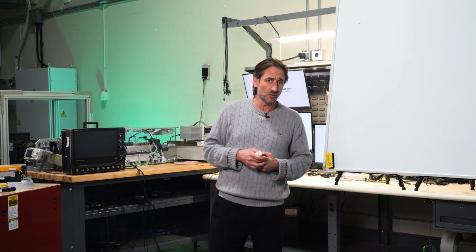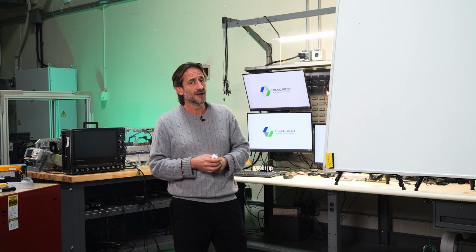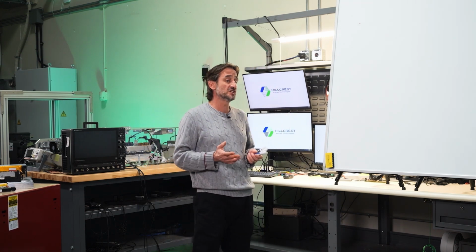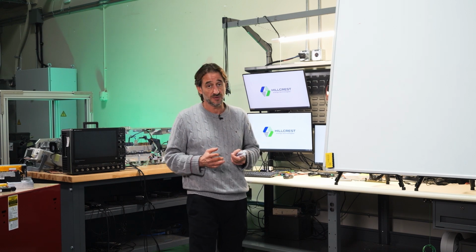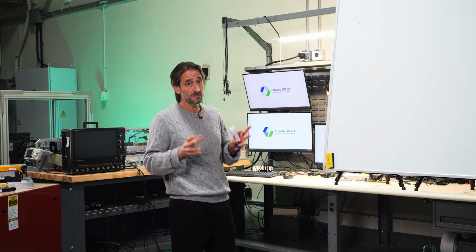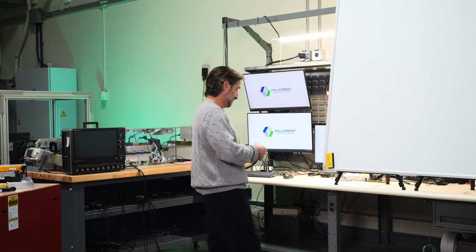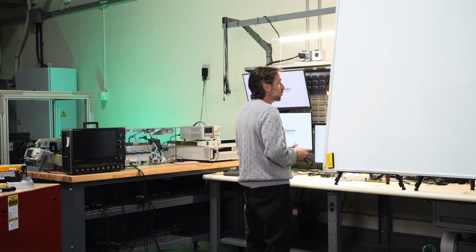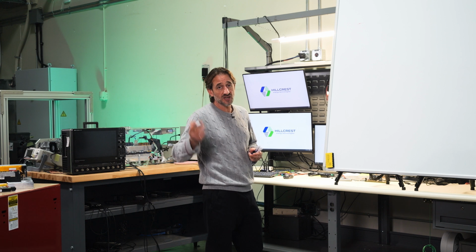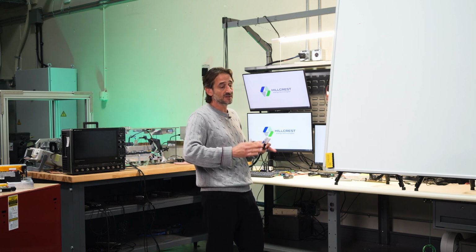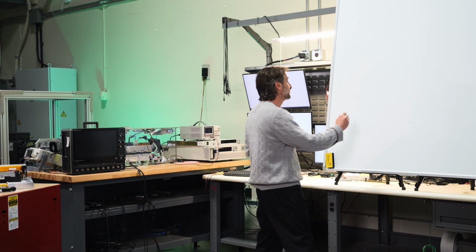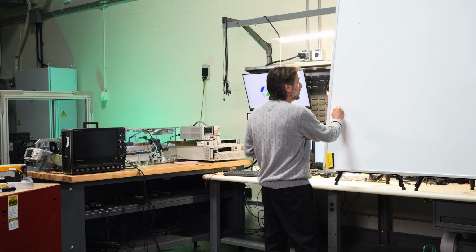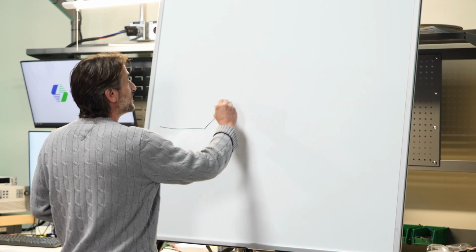So the first thing I want to talk about is how switching losses actually occur in the inverter. Okay, a bit of physics. Let's say I want to turn a switch off. There is current going to a motor, for example, and during that I need to turn off a switch. Let's see how that looks. So the switch was on.